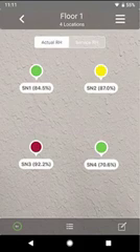The color of the pushpin for each location will be color-coded according to the target RH setting for the sensor map. If the most recent reading is below the target RH, the pushpin will be green. If the reading is above the target RH but within 5% RH, the pushpin will be yellow, or the pushpin will be red if the most recent reading is more than 5% RH above the target RH. In this example, the target RH is set to 87% RH.